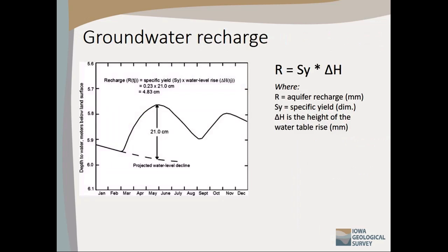So how do we measure recharge? I've talked about it a little bit, but in general, if you do high frequency water table monitoring, you see that it rains, and a groundwater rise occurs. This could be monthly, it could be a day, it doesn't really matter. Rainfall happens, we get a water level rise. Now, we're not filling up a meter of water in a water table situation.